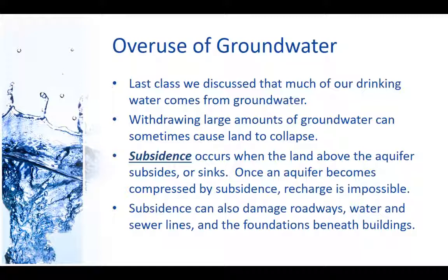Once an aquifer becomes compressed by subsidence, you can't recharge it. I mean, that is a dead aquifer. It is no longer going to hold water. This is what you saw in some of those sections of the San Joaquin when Sutter is holding up his shovel so that you can see where the land used to be versus where it is now. That's how much dropped because it collapsed and crushed the aquifer.